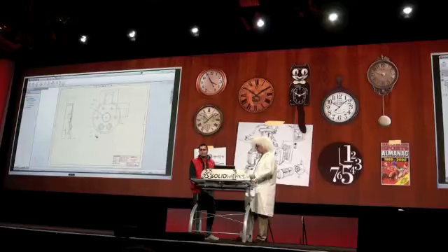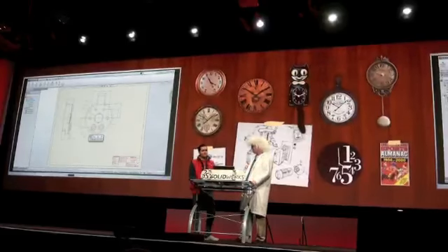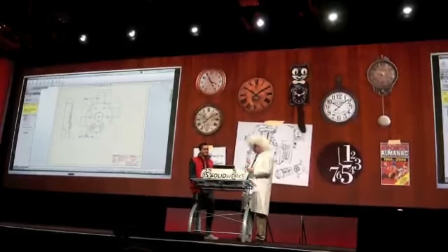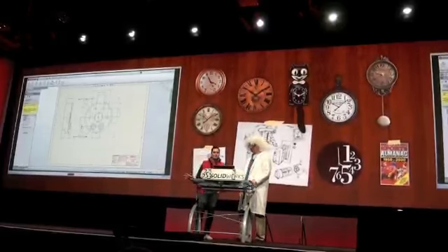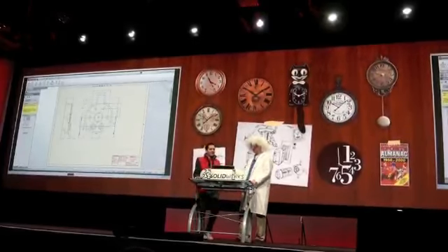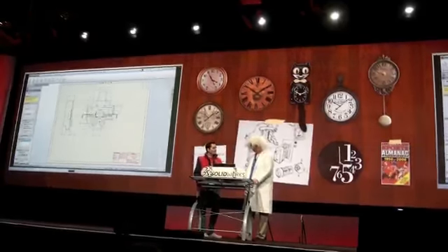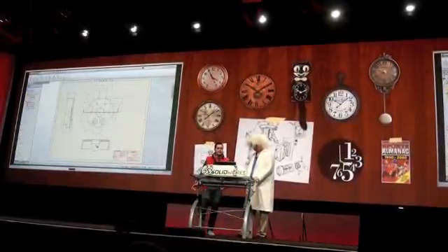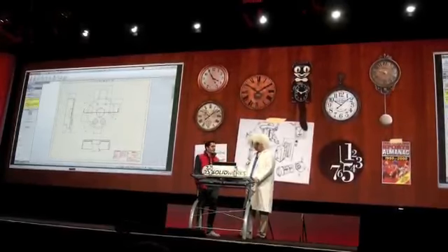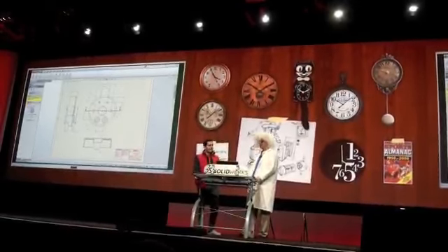That's amazing. Well, you better get going and create some section views to get Strickland off your back and make sure we can get this design fabricated. That's not a problem. With the section expert in SolidWorks 2013, I can whip out those in just a couple of clicks. Click the section tool, tab to change orientation, and auto-flip means I don't have to worry about which side I place the view.